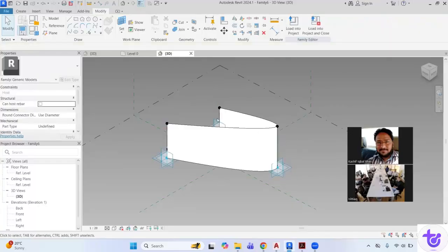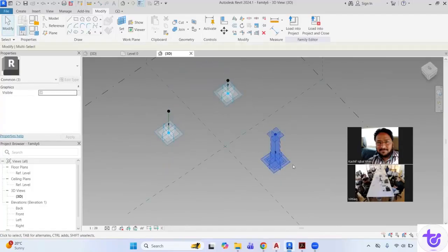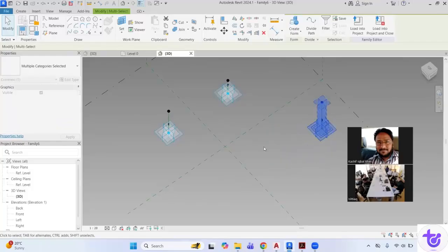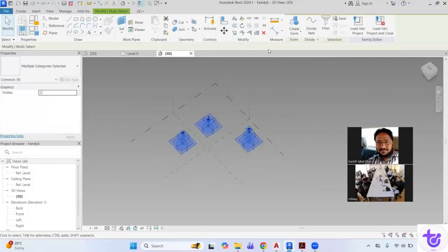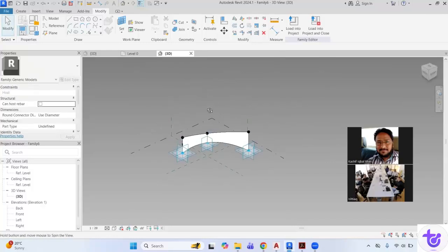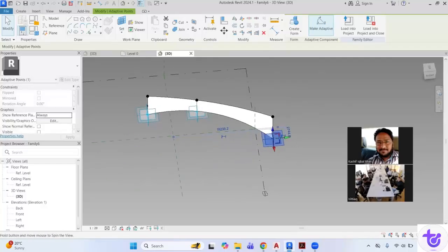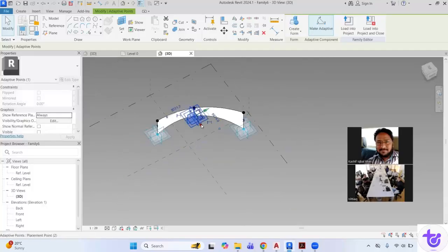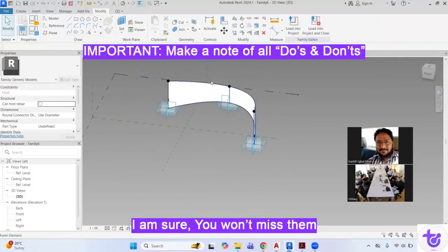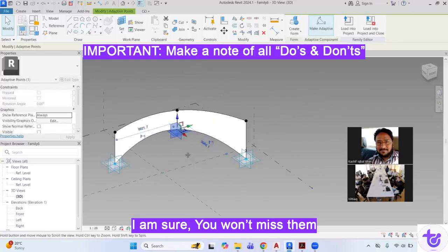Create a form. Now let us just check, just displace this maybe a little away. And then make this form again. Yeah, it is fine. If I check it by moving this here and there, you see the point above is following the point below. Can you see it? In the previous family, it was not doable actually. So it should be checked whether the point above is following the point below or not. It should follow. Now it is working fine.